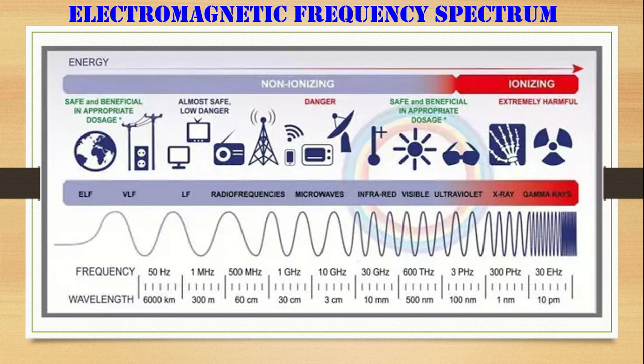We have here another illustration to give us more details. All right, so we have here what we call extremely low frequency, ELF, then very low frequency, then the low frequency. And next here we have the medium frequency, the high frequency, very high frequency, extremely high frequency, and so forth. So the frequency and wavelength are here. For this one, between this VLF and LF, 50 hertz. So in terms of wavelength, we have 6,000 kilometers. That is the wavelength, meaning in one cycle,